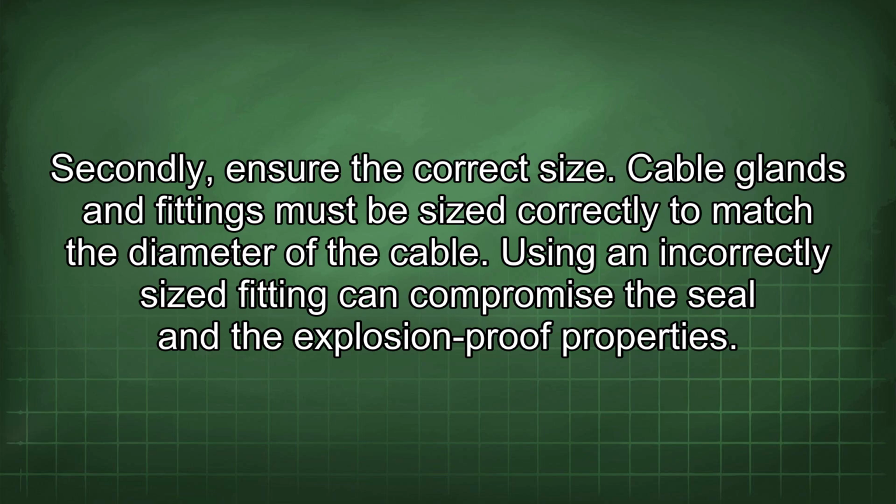Secondly, ensure the correct size. Cable glands and fittings must be sized correctly to match the diameter of the cable. Using an incorrectly sized fitting can compromise the seal and the explosion-proof properties.